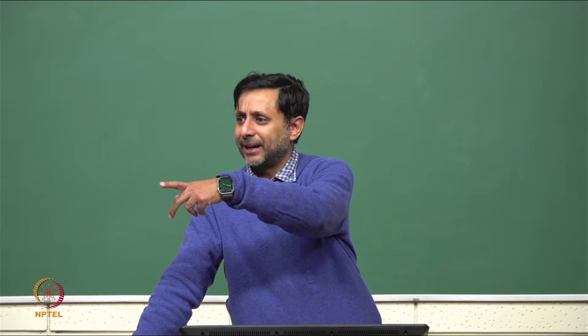And Adib says that it is more than the number of fundamental cut sets. So, the number of fundamental cut sets was n minus 1. So, 1 less than this, okay. And therefore, this cannot possibly be linearly independent, because I am sure I have at least one extra equation, if not more.